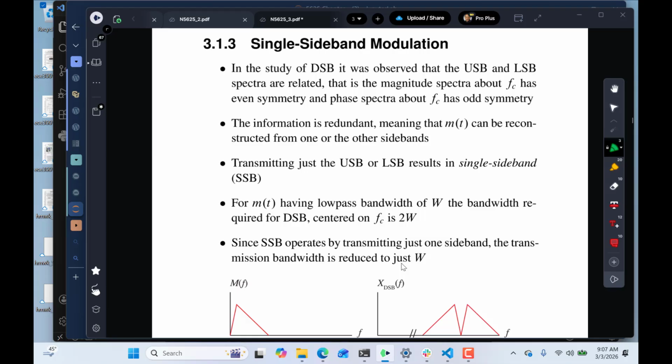Remember, we talked about spectral occupancy, or spectrum, as being a natural resource. So the telephone company a long time ago realized that if they wanted to have a network in the analog domain, they could have a switching center where they would use single sideband and pack as many telephone channels together as possible and send them around the country, or around a community with wires, twisted pair wires.